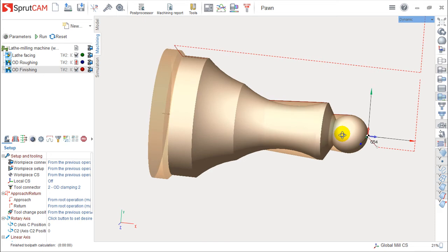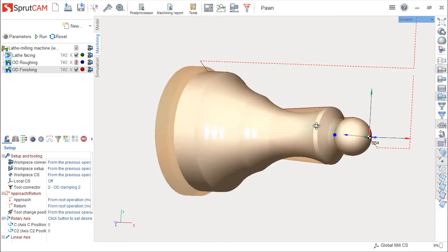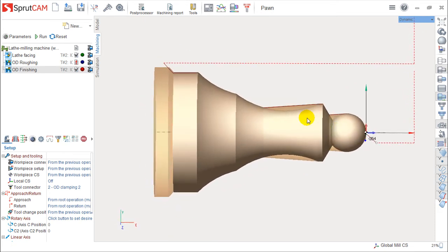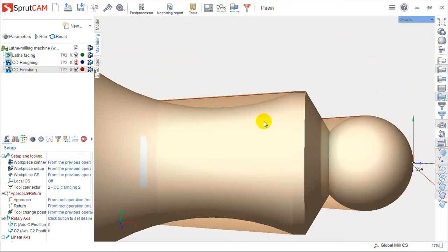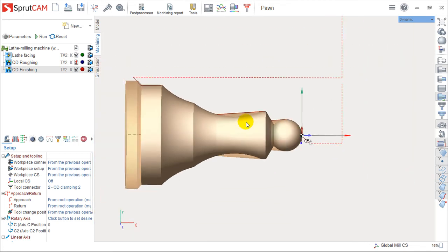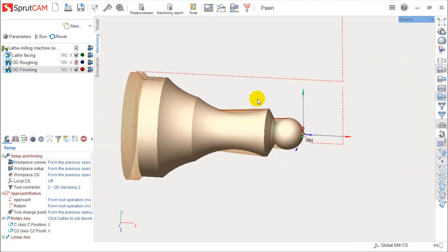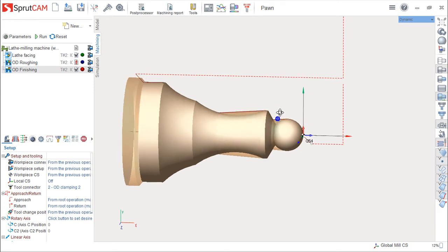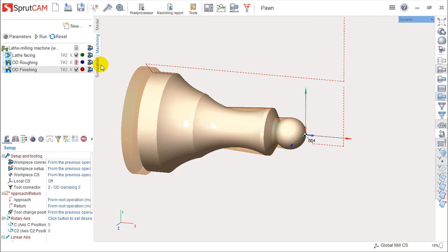As you can see, it depends on the shape, and it also depends on the shape of the tool, because even though we have this shape here, the tool that we've chosen cannot come into this area and take this material, because probably it will make a collision. And here the same. So either we should have another type of tool, or it happens like the thing you are seeing now.